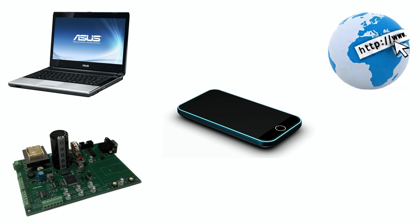For the purposes of this video, a wireless tethered cell phone is used as a router. The reason for this is because the university Wi-Fi doesn't allow direct communication between devices. In our case, the laptop is connected to the cell phone, and the MatchPort is connected to the cell phone. The laptop also has a web server running, which is how the data is transferred through the web. The MatchPort will send an HTTP POST message to the web server, and the web server will respond with control signals for the power monitor to interpret.